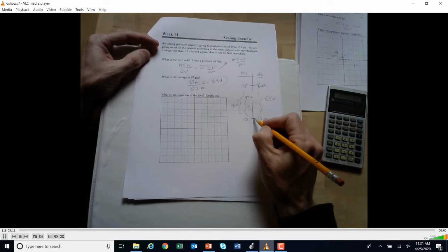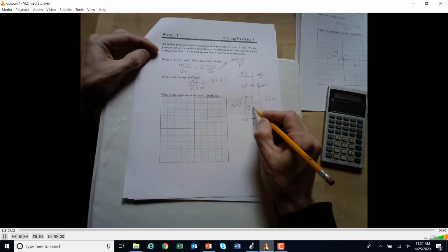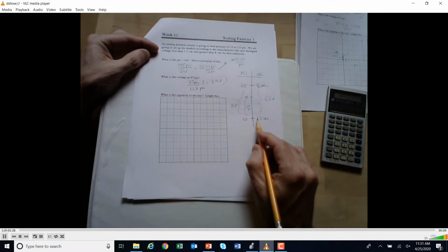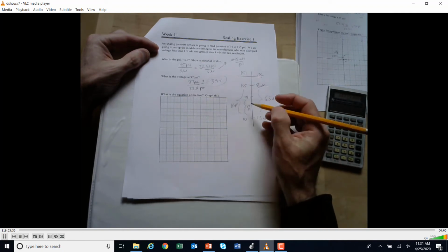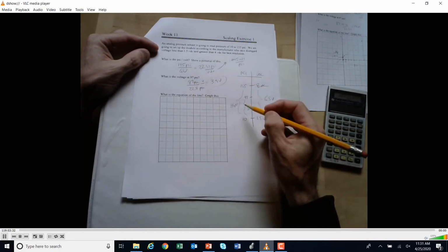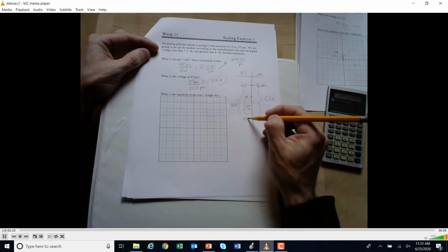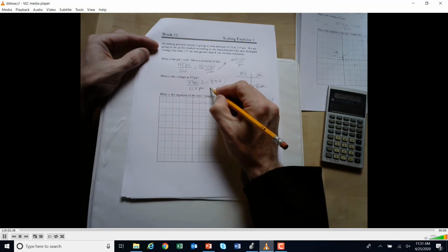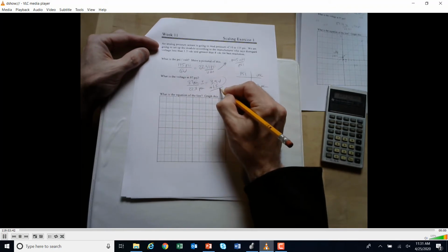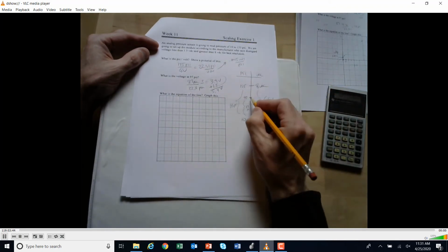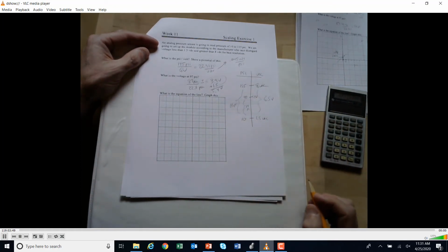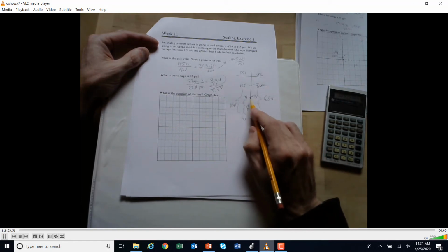Well, that is how far we moved up the scale. But remember, we started at 1.5. So we need to add 3.9 volts onto 1.5. Just like we added 97, we went up 87 on top of 10. We go 3.9 on top of 1.5. So 3.9 plus 1.5 is 5.4 volts. So right here at 5.4 volts, we would be getting 97 psi.